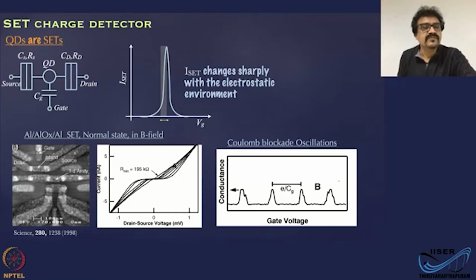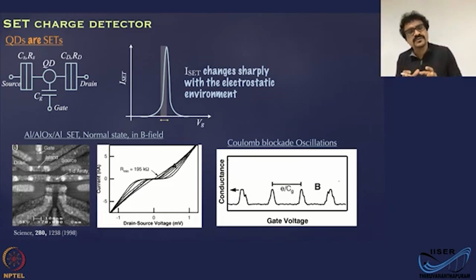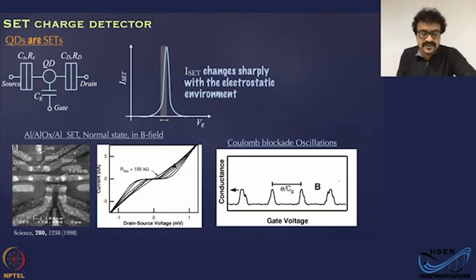Usually, when we say single electron transistor, those are always large quantum dots where you observe Coulomb blockade. And the term quantum dots is generally reserved for systems where you see single particle levels. And quite often, single electron transistors refer to charge sensing quantum dots, and quantum dots refer to the system where you are studying the dynamics of the charges. The term SETs or single electron transistors usually refers to the charge sensor.